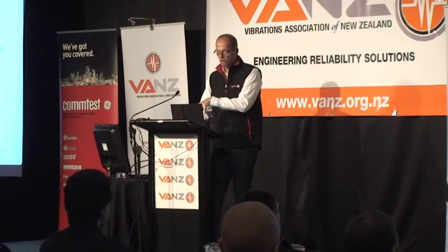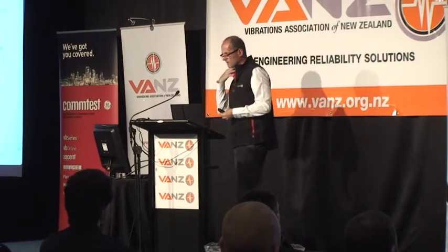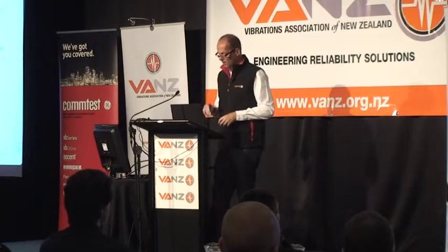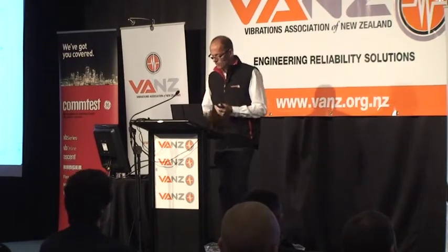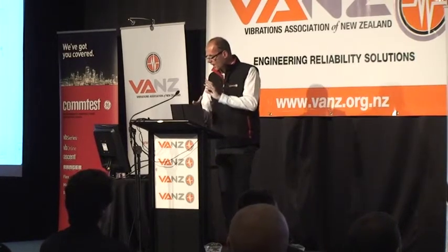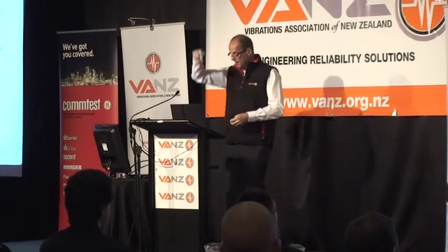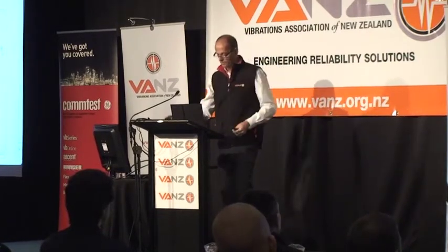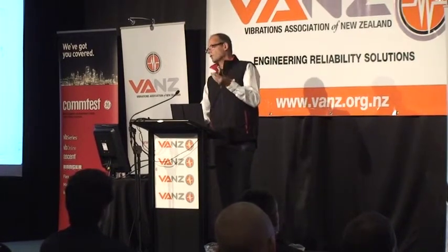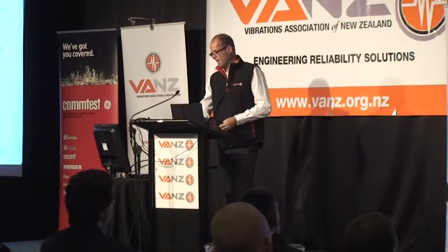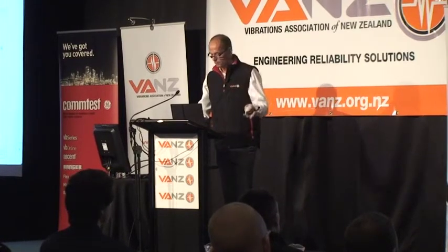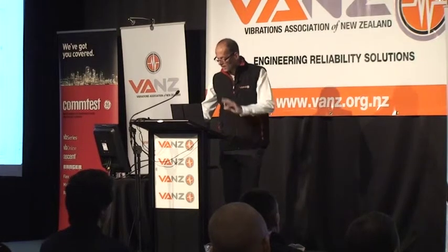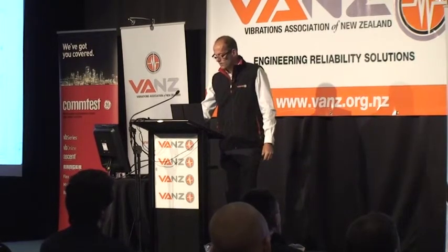So what you're seeing there in red is sort of like what you were seeing from the accelerometer just a moment ago. So okay, that's all good, but what we'd like to do is really be able to say, well, there's the grey vibration, the green vibration, and the orange vibration from those different sources. And that's what the FFT does, the fast Fourier transform, or the spectrum. And so there's our 3 sources.